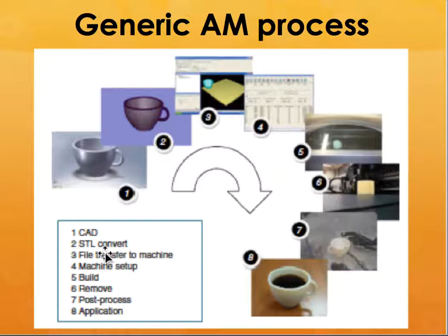And then you have to set up the machine such that, say for example, if there are overhangs and undercuts and things like that, it will install the support material there, and then it'll tell you the XYZ information for each of those layers, and then you can press go and the machine will start building the part, and then after that you remove it from the build envelope.